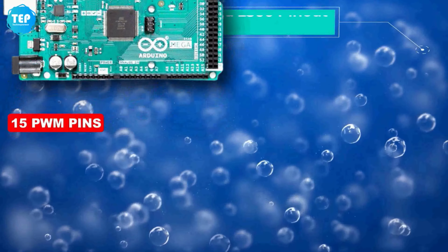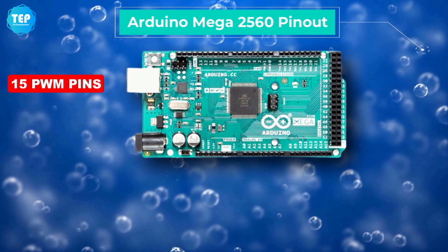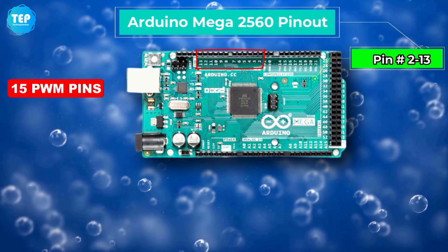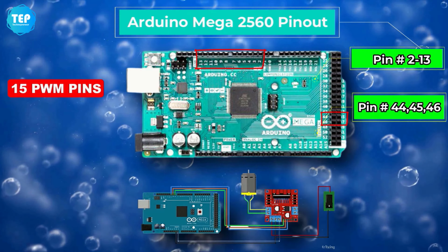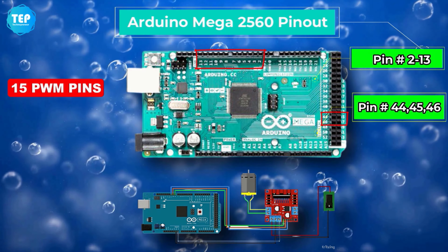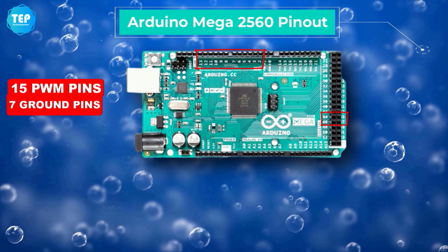For example, we also have 15 PWM pins in Arduino Mega, which are used to generate PWM signals. Pin number 2 to 13 are all PWM pins, and pin number 44, 45 and 46 are also PWM pins. If you want to control the speed of a DC motor, then you need to use any of these PWM pins. It also has 7 ground pins in total, distributed over the board.